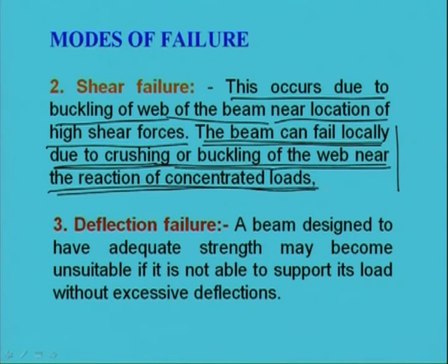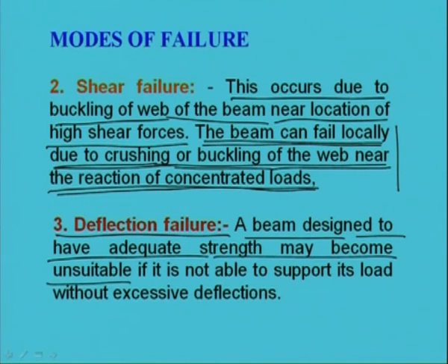Another failure is termed deflection failure. A beam designed to have adequate strength may become unsuitable if it is not able to support its load without excessive deflection. That means if excessive deflection occurs, there is no meaning in providing adequate strength, because deflection will cause a lot of problems.